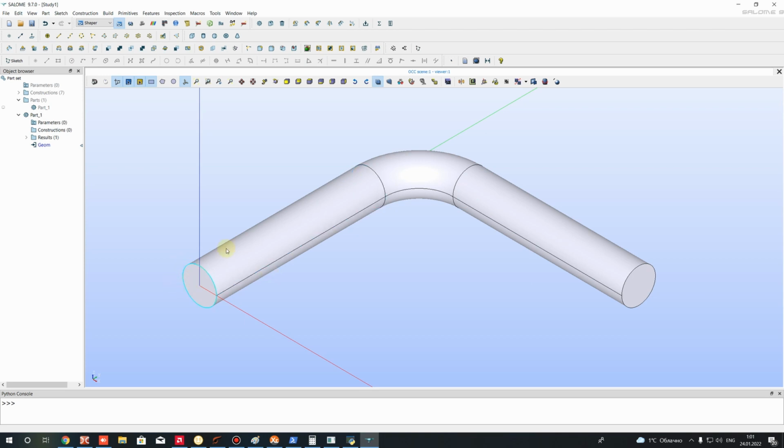For the inlet we will set something like mass flow rate, and on the outlet of the flow we set static pressure. For the wall we will set a no slip boundary condition. It means that we will get friction losses, the hydraulic losses, from interaction between the fluid flow and the external wall of a pipe.